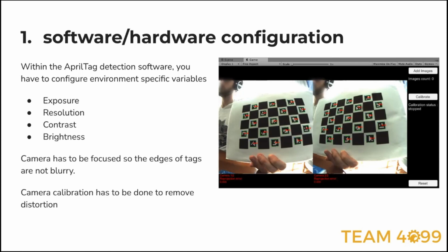So if light's coming in and then I use my camera model to estimate where that light came from, how accurate is that math? How accurate is that reprojection compared to where it actually came from? And so you want to lower that reprojection error as much as you can, because that reprojection is used for the actual detection of AprilTags and getting your pose information.